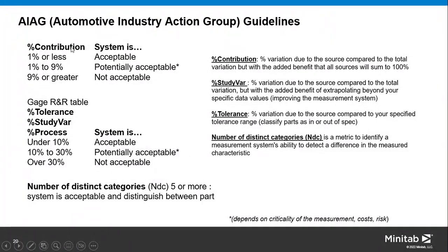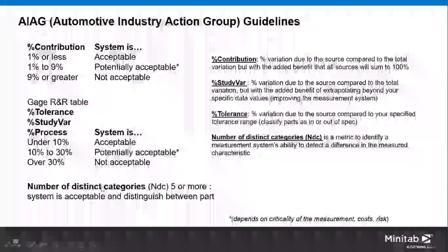Okay, so maybe you look at other standards or other practitioners who use the NDC first, look at the NDC first, and then after that look at the contribution and the tolerance to assess whether the measurement system is acceptable or not. Okay, there is no rule that you must use the NDC first and then contribution.